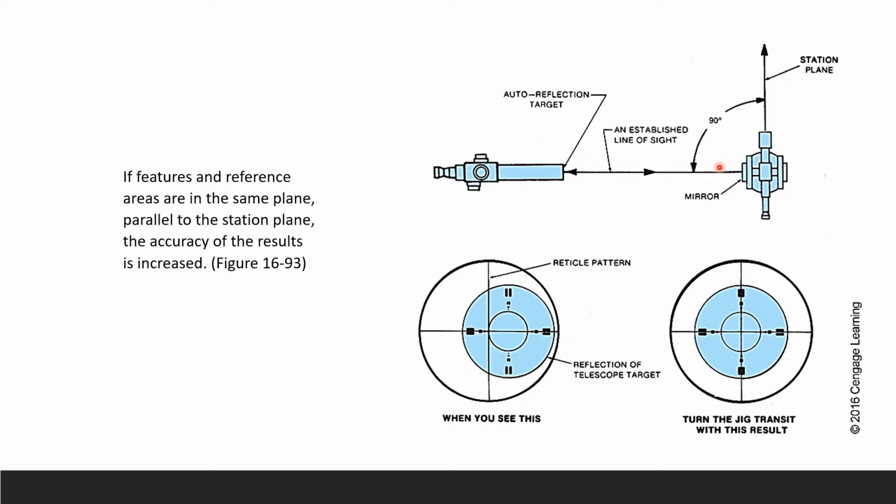It is automatically reflecting the light rays coming into this mirror. And this is our LOS, line of sight. You have to get this perfectly horizontal, 90 degrees to your plane, and this is how we create it, by using this instrument and that instrument together.